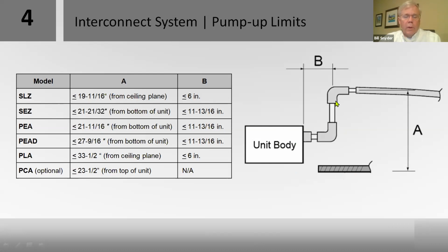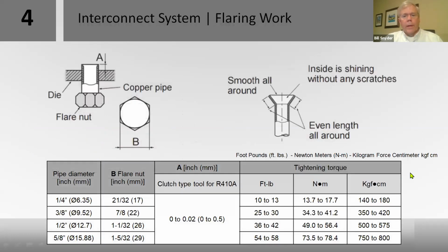and you use whatever size pipe comes out of here. I think it's 1.25 inches, has to go up to this point, then you can go into a standard drain fitting from here on out. So just be careful with that. Some people say, well, it says I can go 33 inches, so I went from there up 33 inches. Won't work. So just be aware of that.